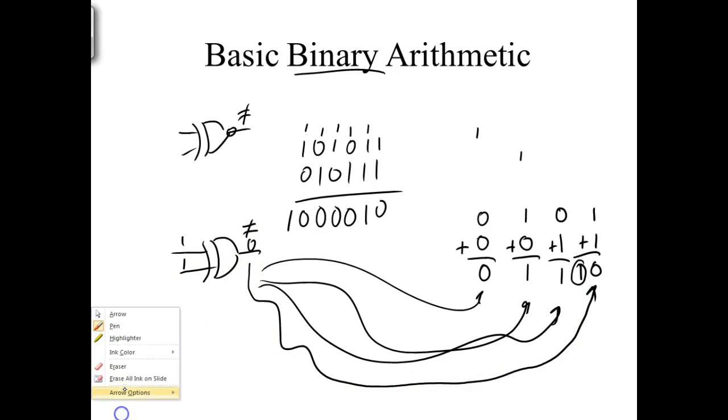So what would happen if I came over here and tapped off right here and tapped off right there and put an AND gate right there? Then this last one would give you that right there. So this little circuit right here would add 2 binary bits. So this is called an adder. It's called a half adder. It's called a half adder because it can't pick up a carry.